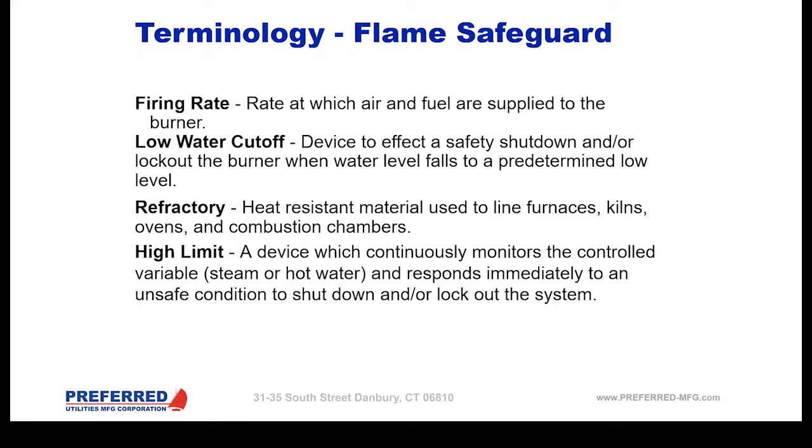Low water cutoff. This device is effectively a safety shutdown or lockout of the burner when the water level falls to a predetermined low level. And as David mentioned earlier, in a lot of applications where they may have an interruption of water flow for whatever reason, they will have a low water cutoff slightly above the low water cutoff, which will allow a shutdown and a restart once the water level has been reestablished.